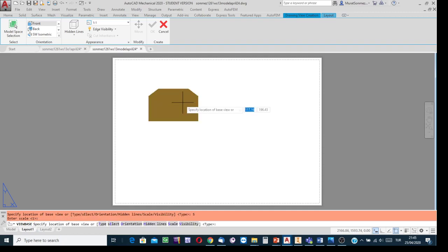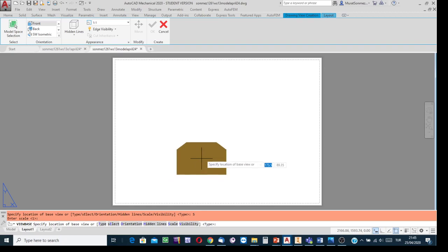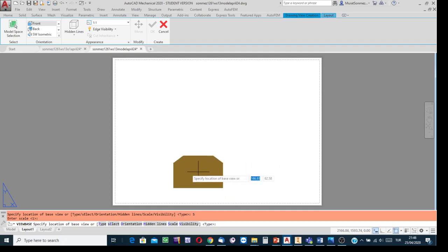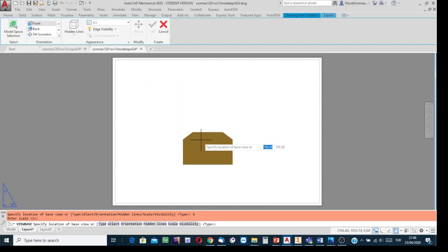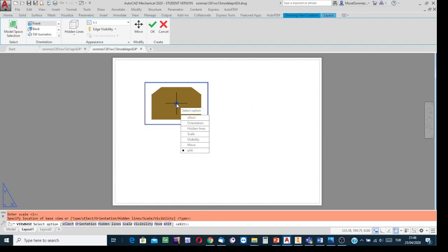Press enter. And then, from the learning outcome, say studying the theory part, you learned clearly, I am sure, that in the first quadrant projection, the front view is created not here, not here, not here, but there. If there will be 3 views, the front view is to be drafted using this part of the drawing paper. So move the cursor together with the simulated view to this place, and then with a click anchor it. And then finish the base view creation stage, clicking on the exit option.